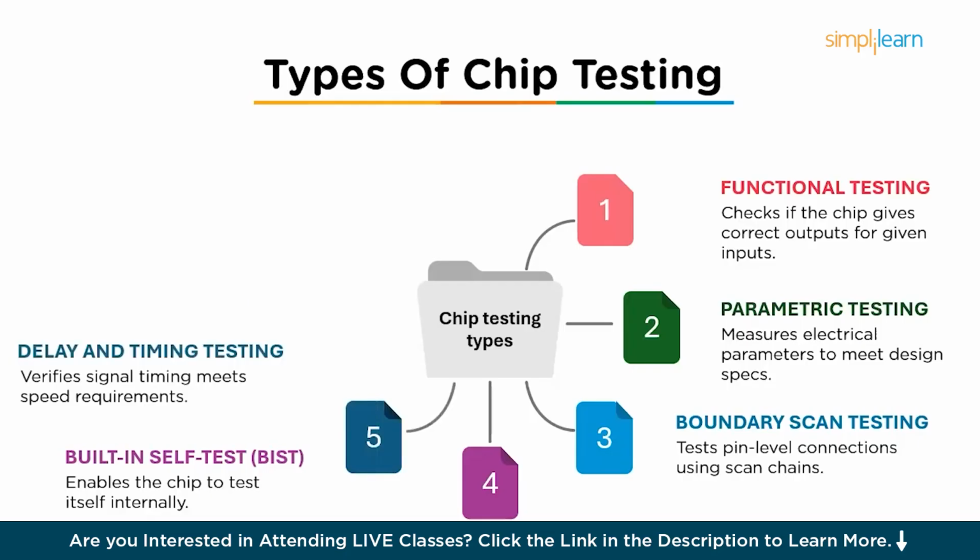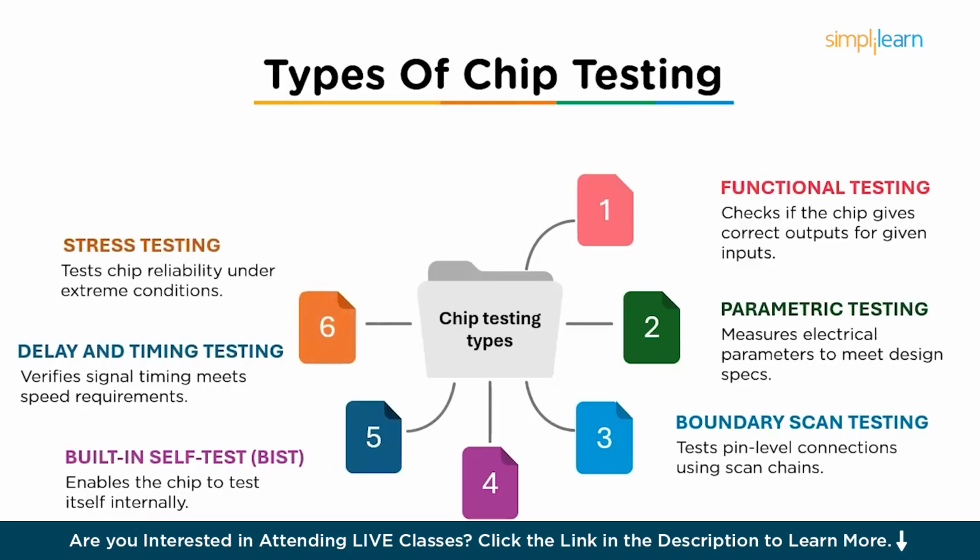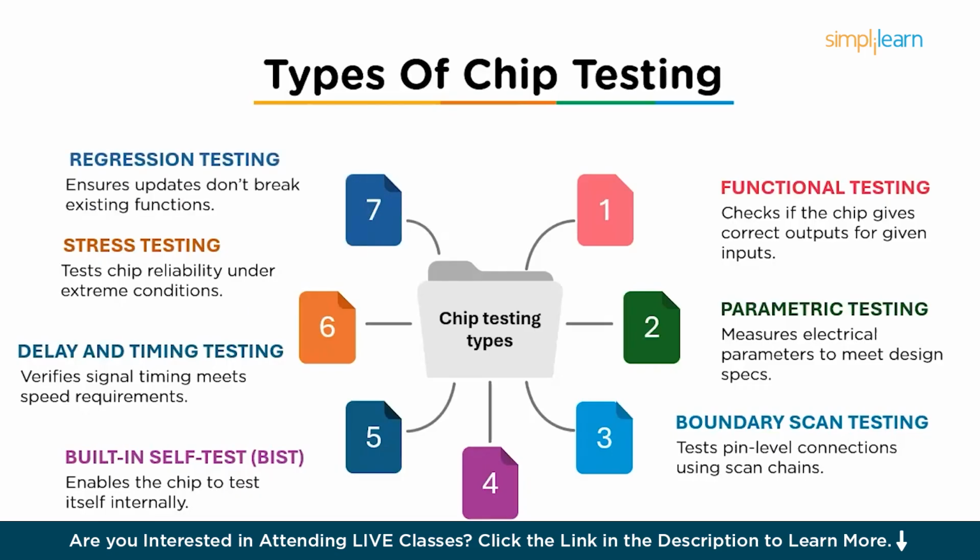Then comes delay and timing testing. It verifies that signal timing meets speed requirements. Then comes stress testing. It tests chip reliability under extreme conditions. Then comes regression testing, which ensures that updates don't break existing functions.